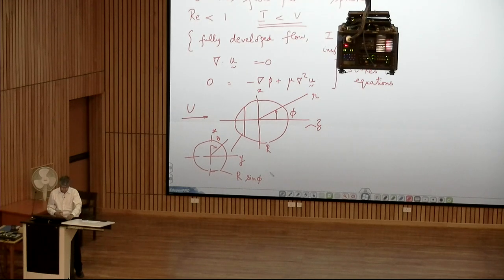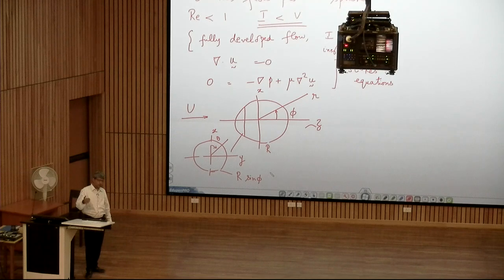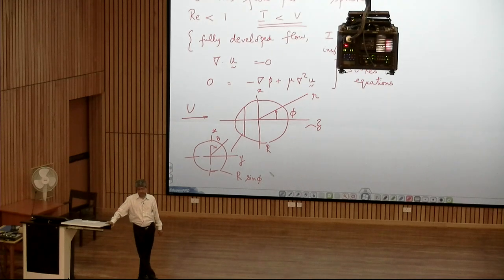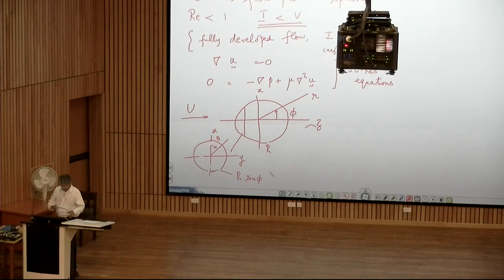So, this entire development is in the text. I am not going to solve these equations, but I gave you a hint. The first step in solving such equations is to decouple velocity and pressure. So you do a del dot of the momentum equation, you get del squared p equal to 0, solve for pressure, put that in the momentum equation, and you have a Poisson equation for velocity that can be solved. So these solutions can be obtained using classical tools as outlined by Kreyszig or equivalent. Algebraically, it becomes a little more complicated because of spherical coordinates, where the curvature terms are, let us say, formidable.